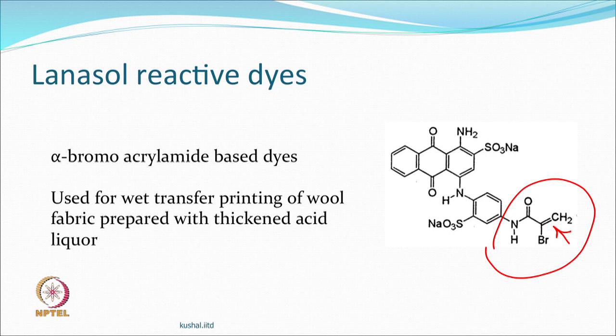So, this is a reactive dye. You have basically an alkali and some viscosity modifier, so that the spread does not take place so much. Like when you have a tailing effect in a dyeing padding system, you add sodium alginate and some such high molecular weight compound, so that the tailing is reduced. Here also there is a bit of a viscosity modifier, but still it is a padding process and not a paste process, and that is the kind of thing basically. Alkali is there because you like it to be fixed.